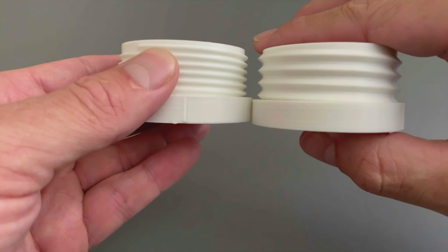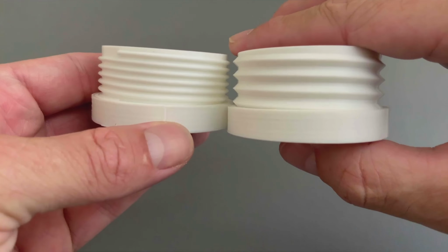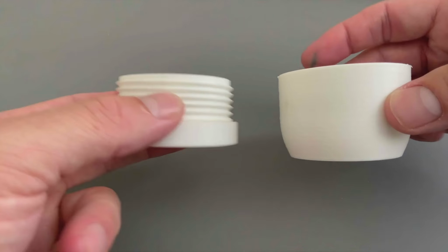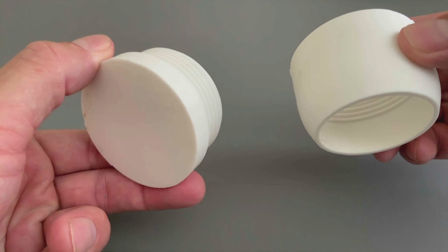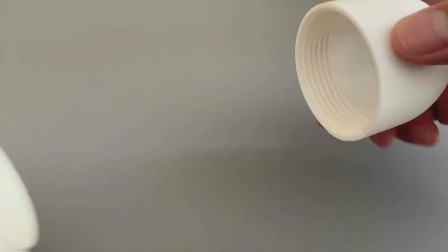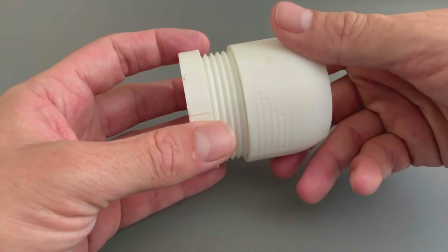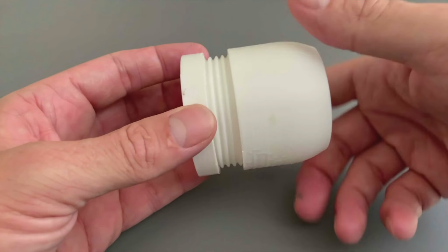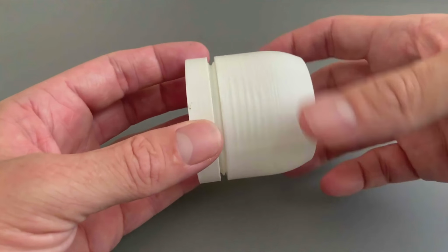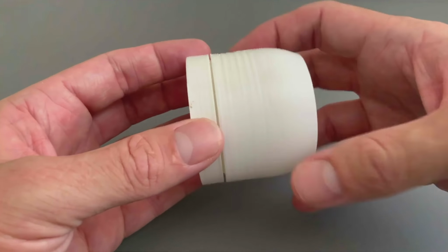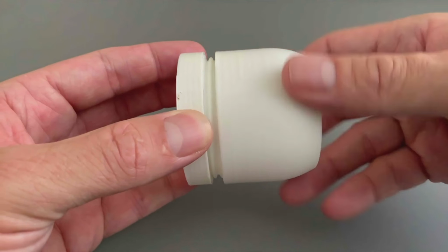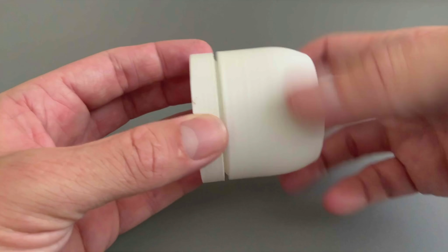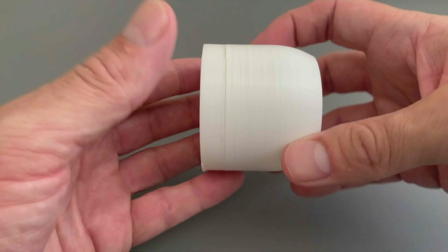Remember, like in my design, the threading was an individual object, which later I fused to the bottle. And also as a tip for test pieces, so I wanted to figure out if my threading is good. You see, I only printed a piece of my cap and a piece of my bottle. Why should I print everything completely? And now when I put this together, I know that with the printing machine I have right now, this threading actually works out really good. I could maybe even try to get it a tick tighter, but if I continue rotating it, it seals perfectly.